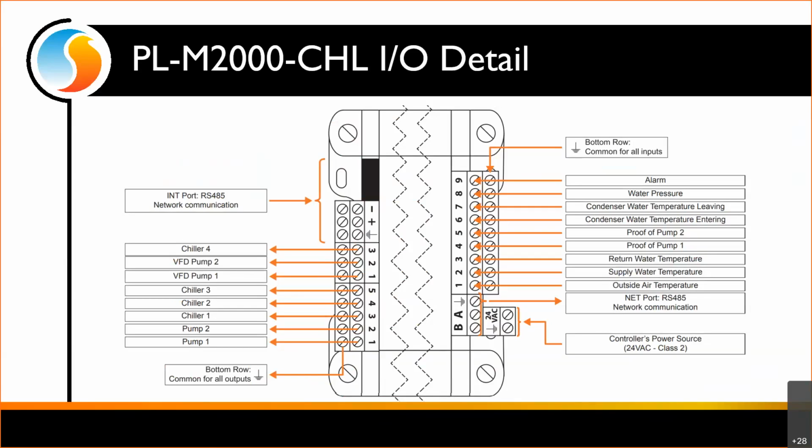Okay. Analog outputs 1 and 2 are going to vary. They're going to be going to their respective pumps. So pump 1, the run command is going to come from DO1. The speed command is going to come from AO1. It's going to be controlling off of the pressure that it's reading on input 8. We'll have the opportunity to set this all up in the software. Okay, so just remember that chiller 4, even though it is an on-off command, it is going to be only a 10-volt maximum on there.